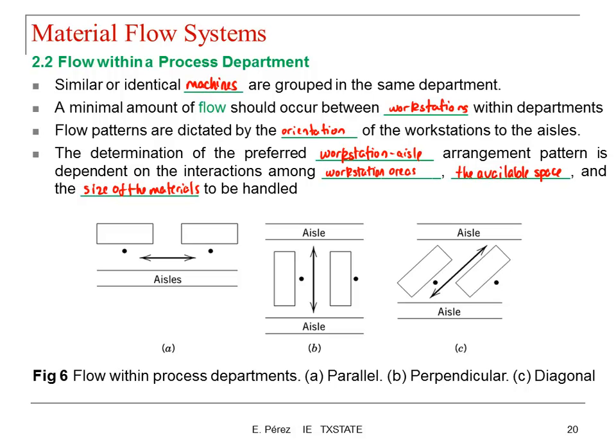You might put them in a diagonal type of way, but that limits your flexibility, because if you have a limitation of space, you need to plan for having at least 2 aisles for that type of design, one for moving one direction and one for the other direction, and that limits your flexibility in terms of production.